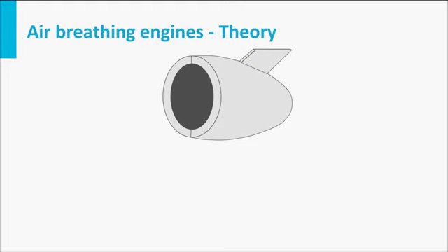So let's have a look at this with our engine as a reference frame. So here we see an engine, an air-breathing engine as we call it, because there is a certain amount of air that goes in. And there we have a speed. The entry speed is the true airspeed of the aircraft, V0. And the mass which enters the engine is indicated by the mass flow.